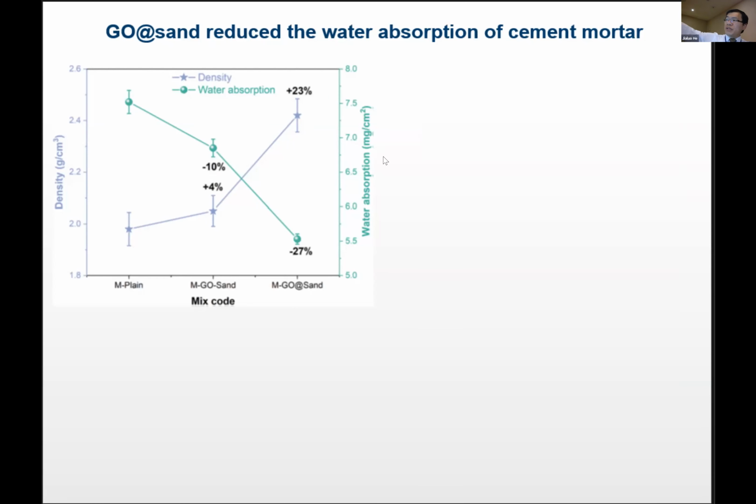And also you're seeing reduction in water absorptivity, which is highly desirable, because the slower the water can get into the concrete, the more durable the concrete. Usually, I would say 90% of distress is associated with water, say freeze-thaw damage or chloride-induced corrosion or sulfate attack. Many of those things are related to the presence of water. If you can keep the concrete relatively dry, those distresses go away. And of course, we're seeing a little bit increased density because of the denser microstructure here.